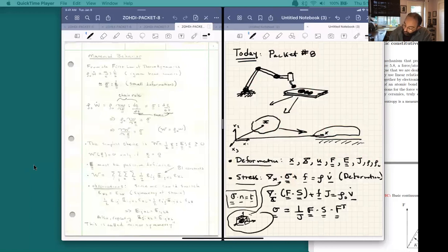There's also the volume forces, or forces per unit volume, the density in the current configuration, and of course the time derivative of the velocity. So that's the classical equation of the balance of linear momentum. And what we realized is because that thing is posed on a deformed configuration where it might not be easy to know beforehand where that configuration is, oftentimes we'll rewind the movie and go back to the original starting configuration, which is shown here. And in the starting configuration, we formulate the differential equation there.